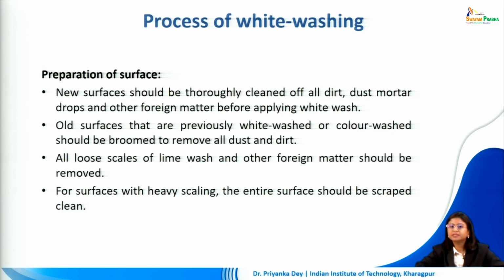Then we have to prepare the surface. So new surfaces should be thoroughly cleaned of all dirt, dust, mortar drops and other foreign matter before applying the whitewash.